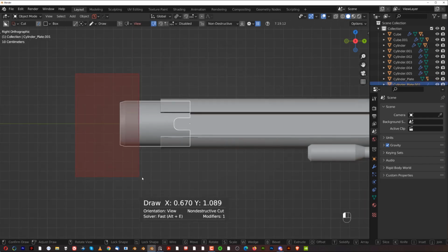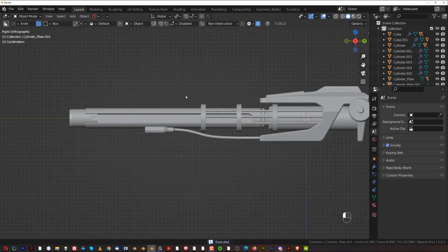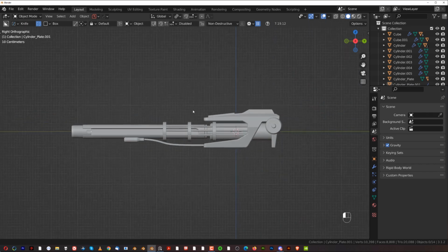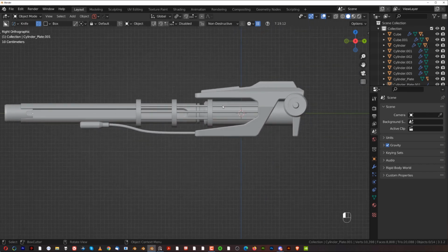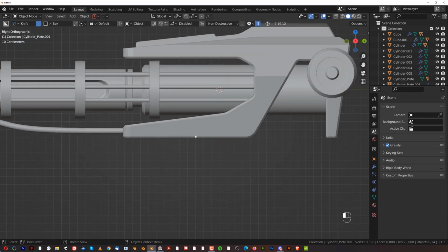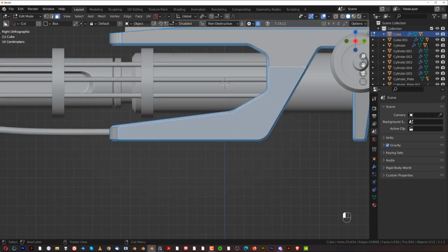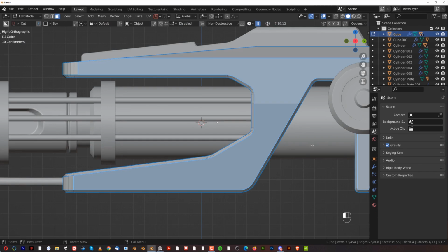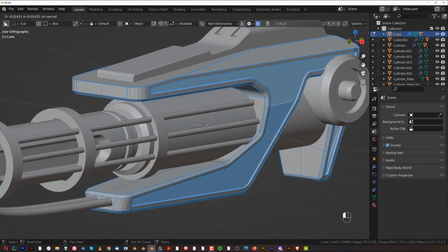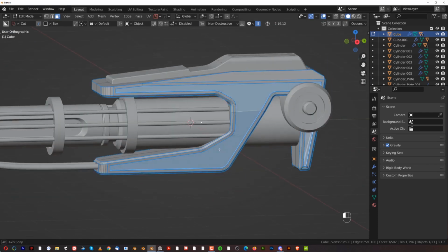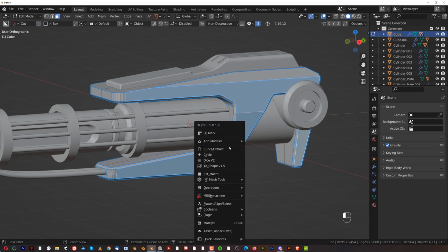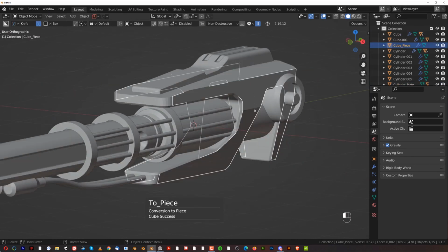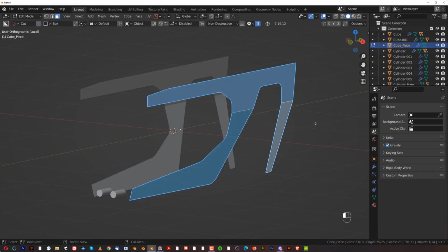And now, you know, now it's all about basically adding details. But for adding details, you can also consult some references and start playing with shapes. Like for example, here we could create some structural piece. So we could grab this entire face, in fact all over it, and we could insert it, like this, and extrude it inwards. Or even better, what we could do is borrow this entire face, this one, and then we could insert it,